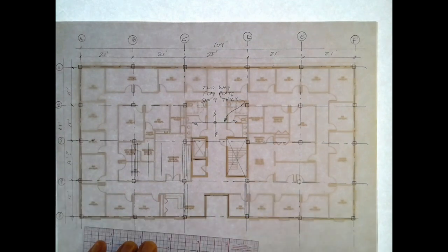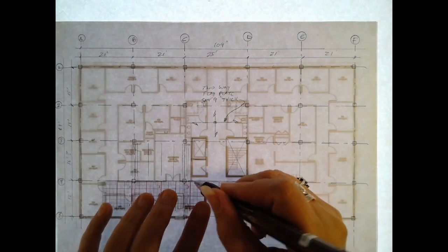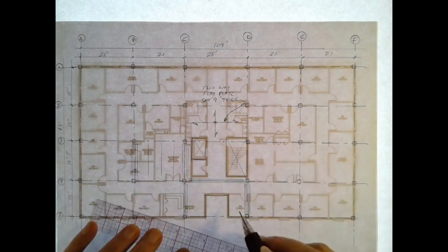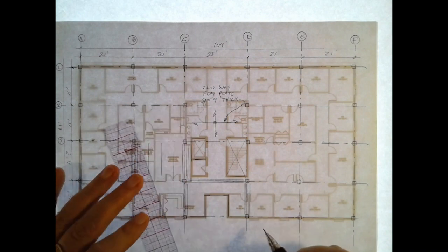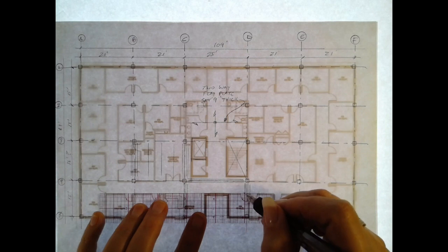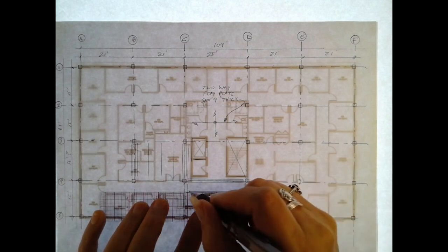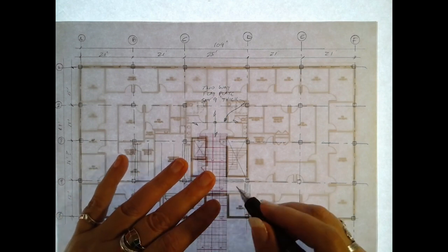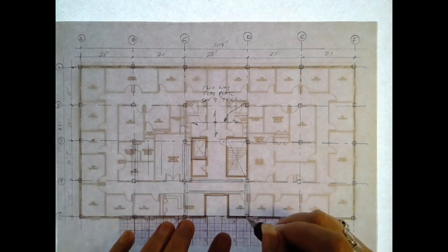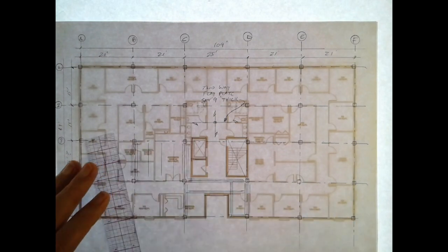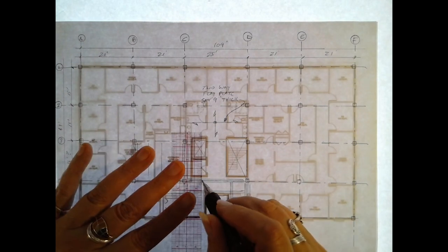These are actually called column bands, I believe. Column reinforcing bands. And so we have one right here. And the break, well, we have to make elements kind of cantilever across here. We can put some extra reinforcement right here. This is a long way to cantilever, so I think we're going to have to double cantilever. So reinforcement would go over here, and this would actually go over here to carry that. So they work together, and that's how we'd be reinforcing an opening.